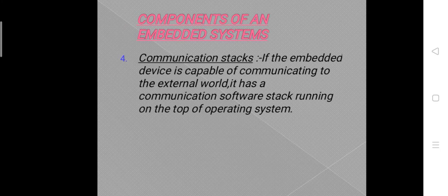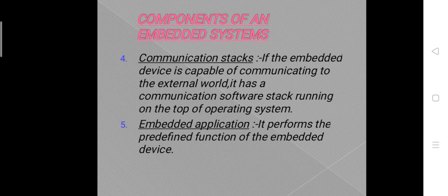Next one is a communication stack. So if the embedded system is capable of communicating to the external world, it has a communication software stack running on top of the operating system. So it could be protocols related with Wi-Fi, Zigbee, Bluetooth, etc. Then we may have embedded application. It performs the predefined function of the embedded device. Actually the application is nothing but software that provides required services to the users.